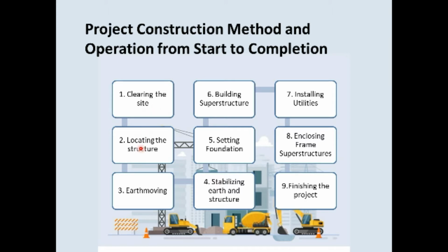Number 2 is locating the structure. 3 is earth moving. 4 is stabilizing earth and structure. 5, setting foundation. Then, building superstructure. 7 is installing utilities. 8 is enclosing frame superstructures. And 9 is finishing the projects.